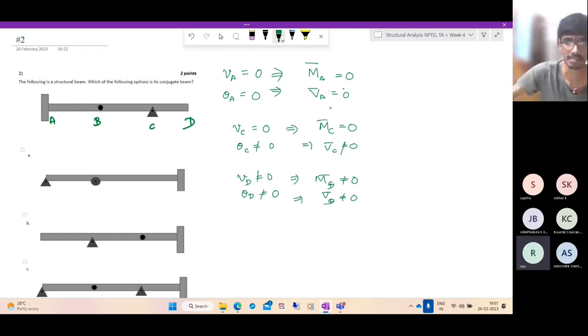Now let us look at point B. That is a bit interesting. So let us subject it to some loading. In that case, how does point B deform? On the left side, it is a hinge, so it does not transmit moments. How does the hinge work? You put two bars like this, and this can rotate independent of these.